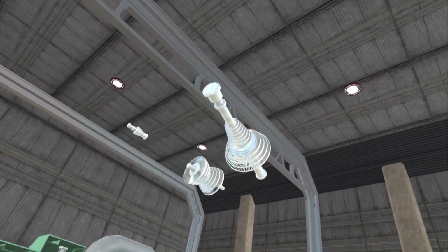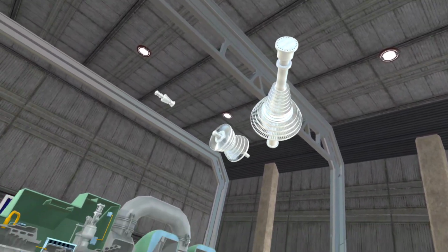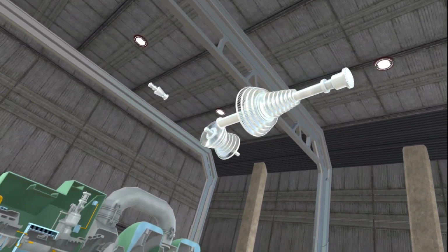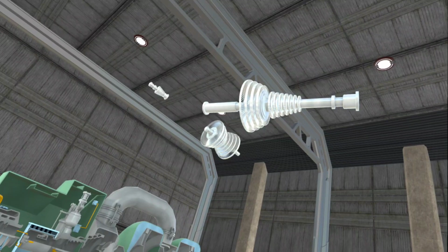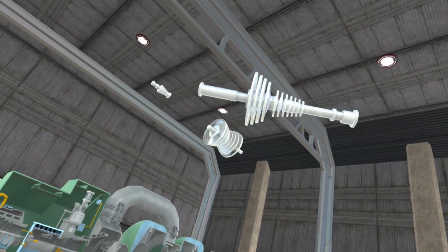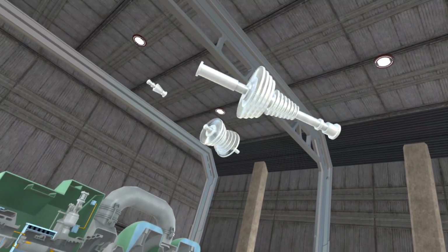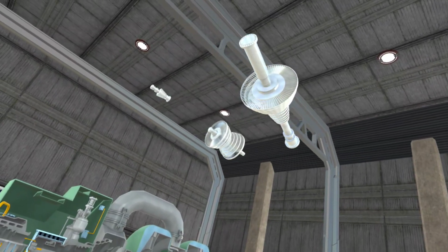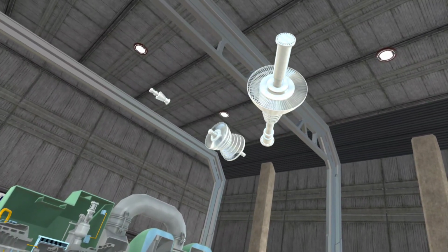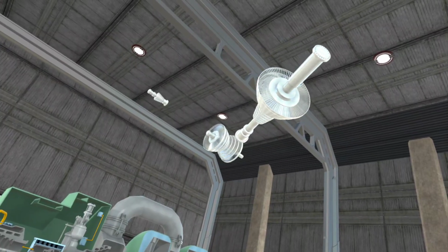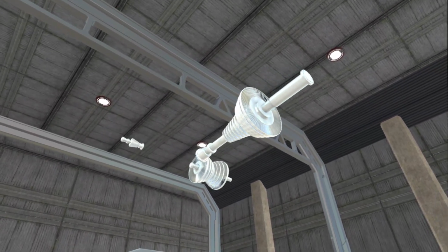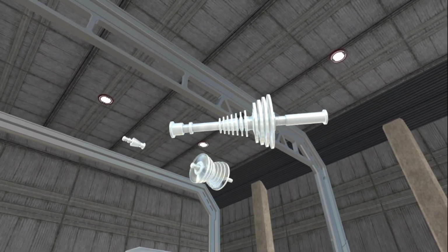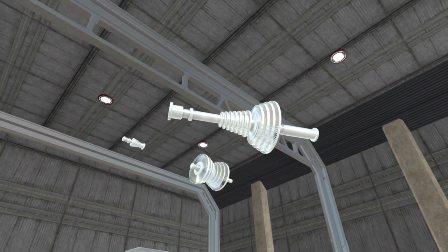The reheated steam from the exhaust of the high-pressure steam turbine drives the intermediate pressure steam turbine, or IP turbine. The exhaust from the HP turbine, called cold reheat steam, or CRH, is sent back to the boiler reheaters. This CRH returns to the IP turbine as hot reheat steam, or HRH. The IP turbine is specially designed to extract work from the intermediate pressure steam.